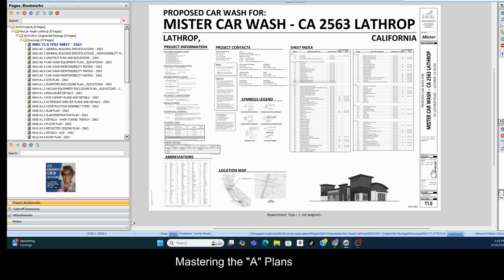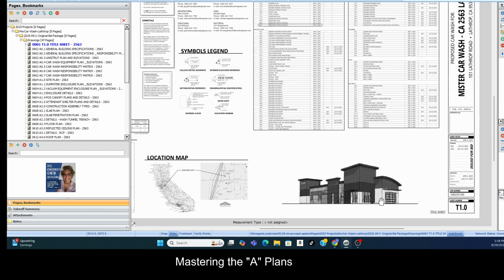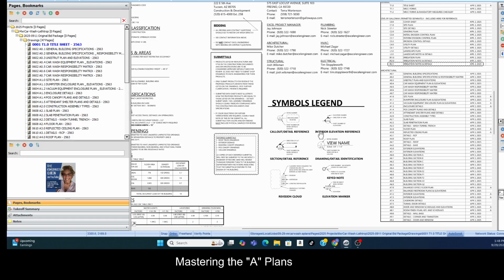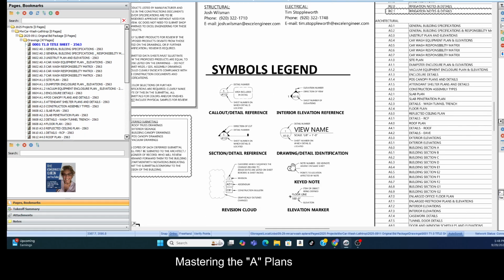But you could also look on the site plan to see if there may be something that they want demoed up out of the ground. Okay, so you want to look at that too, along with the specifications, of course. Okay, so abbreviations, Google Maps, isometric view. This is what it's going to look like when it's finished. Okay, nothing's to scale here, so you can't use it for that. It's just for total information. Owner, architect, engineers that help put the set together, and some basic symbols that we're going to use.